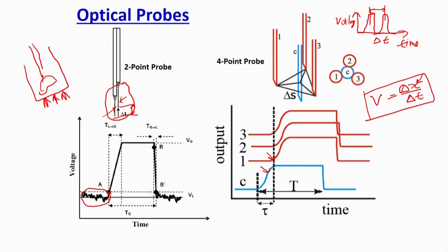Now, in the 2-point probe, the problem is actually the same as with the 2-point hot wire anemometry. If you have a 2-point probe here, you will get only one dimensional velocity. So, in that case you will have only the axial velocity. Suppose you are putting it perpendicular to the flow, in the opposite direction, then you will get only the axial velocity. Now, ideally I want to measure both the radial velocity as well as the theta direction velocity. Even if I assume that there is no theta direction velocity, because there is primarily no motion in the theta direction, we have already discussed that the radial velocity component can be there. So, to measure the radial velocity or the other direction velocities, we have the 4-point probe.